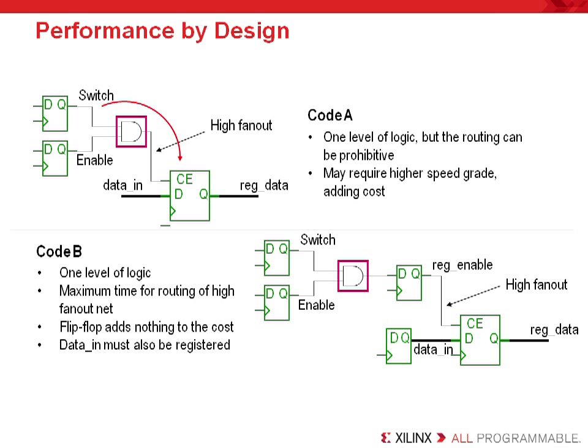The problem with a high fan-out secondary control signal is that there are limited global routing resources inside of your FPGA. Sometimes you can route your highest fan-out control signals on low skew routing resources that are primarily designed for routing high-speed clocks, but since these routing resources are usually at a premium, most customers have some control signals that they must route on general interconnect. Now, this can be compounded by adding LUTs in series to decode the control signal, and suddenly this control signal becomes timing critical. So we recommend that you always consider coding to infer a register on any high fan-out secondary